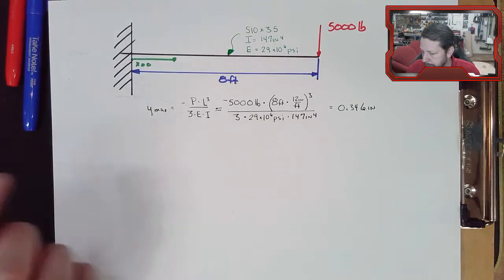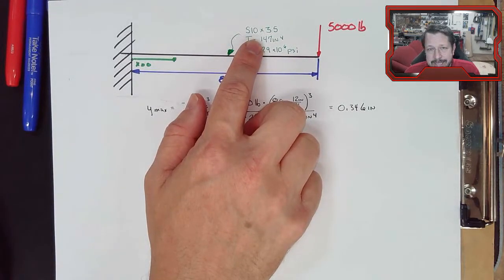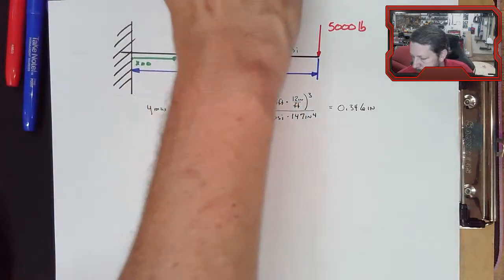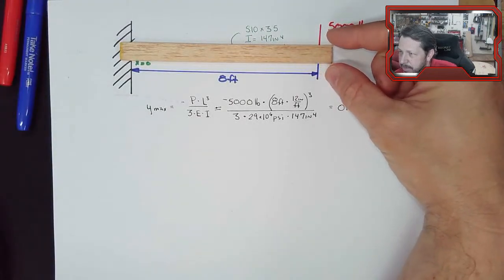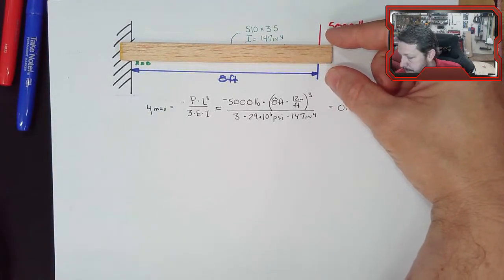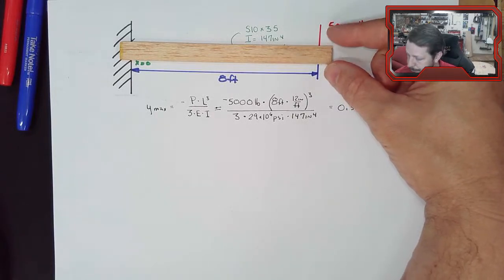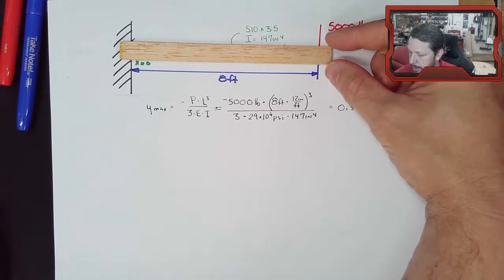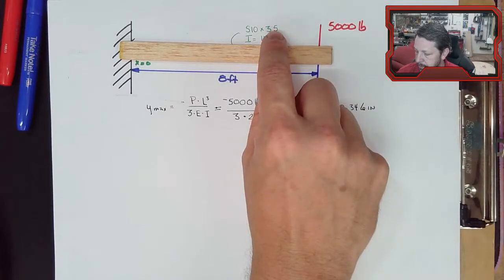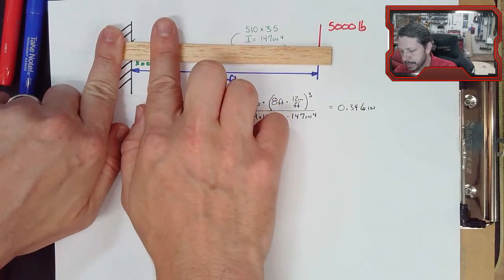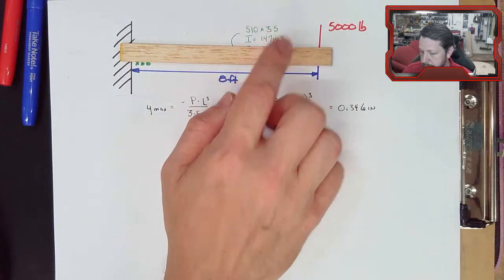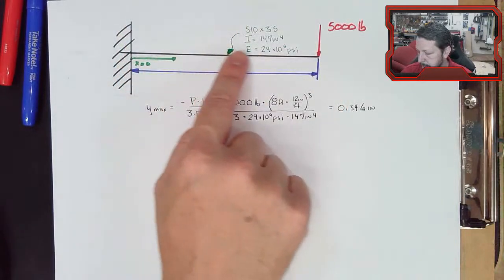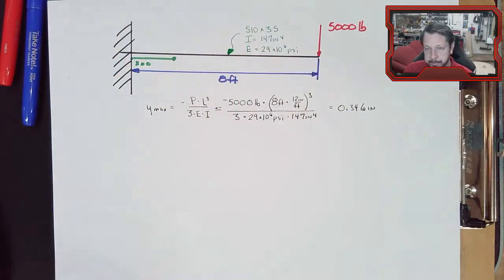So looking at our beam name, it's an S10. So the 10 refers to, if this is our beam, this distance here. How deep, tall is the beam? It's called depth in the charts. So this distance right here would be 10 inches. The 35 refers to, if I took a 1 foot section of this beam, that little section would weigh 35 pounds. So that 35 is just like we had a distributed load all the way across the beam, and it was 35 pounds per foot.